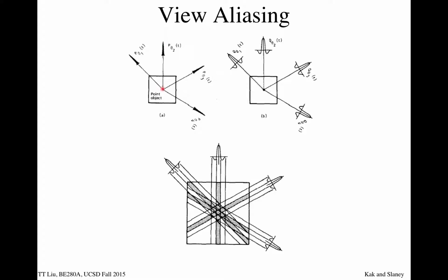So if we have a point object, this is basically our point spread function along L, theta from our sampling, right? We then convolve it with either the inverse Fourier transform of the ramp if we're just going to do it with no filtering, or the inverse Fourier transform of something like a Hamming filter, which smooths it out. Remember we saw these kernels get a little smoother.